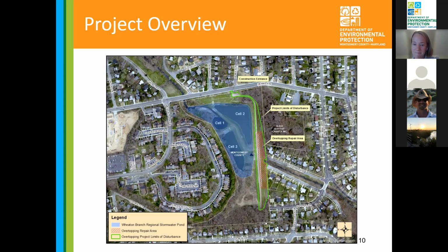The dams are constructed using heavy compaction equipment, and we like them to be well compacted. So we are not worried about having heavy equipment on top of the dam. We will make sure that if there is any settlement as a result, we'll add soil to the top to make sure that we meet those design elevations.